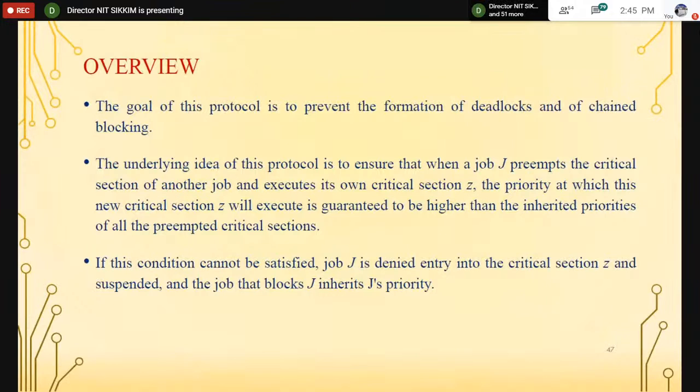if this blocking duration is indefinite, and you do not have determinism in the blocking duration, then your high priority task may fail its deadline. If your high priority task is a critical task and fails its deadline, like yesterday we discussed, the system can be in a disastrous mode and may result in a loss. As we have seen, your whole system was reset. Nothing went wrong, but it could have been a critical task.